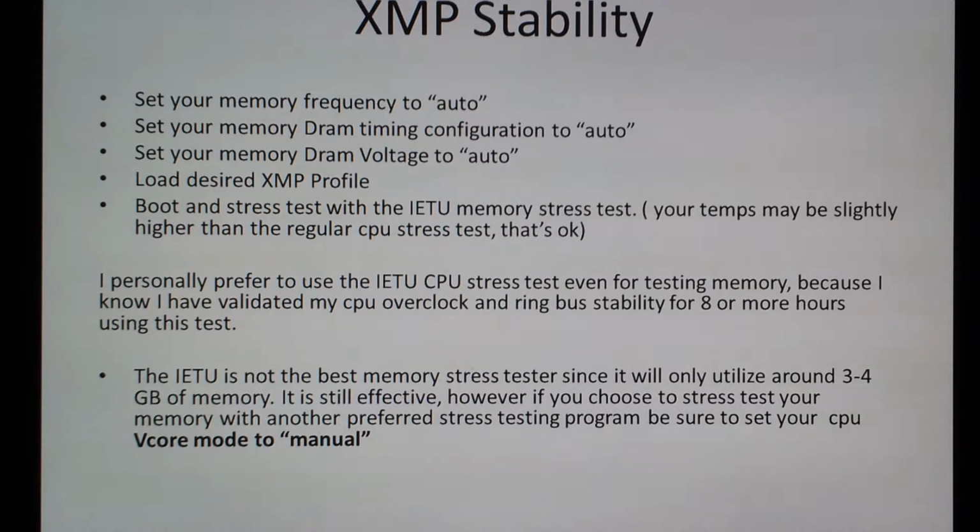I actually prefer to use the Intel Extreme Tuning Utility CPU stress test and not the XTU memory stress test. The reason for this is that I know I validated my CPU for 8 hours under that stress test. I've also validated the CPU ring bus for 8 hours or more under that stress test. So if it crashes within that 8 hours, I basically know that the cause is the memory and not either the CPU or the ring bus.